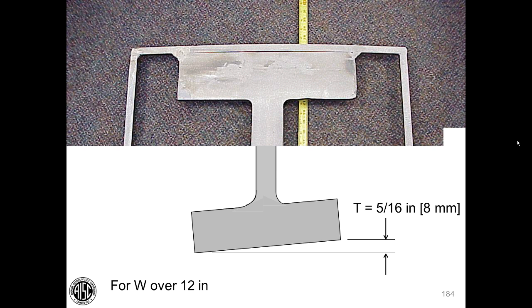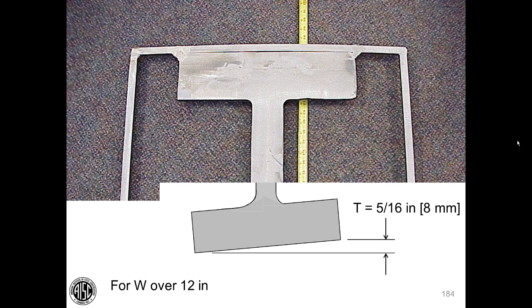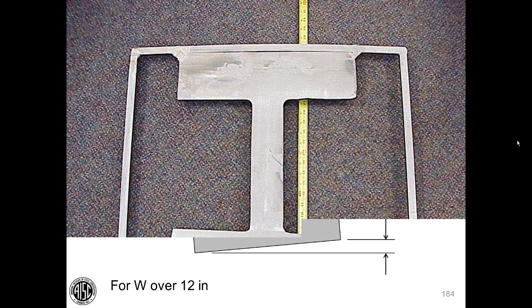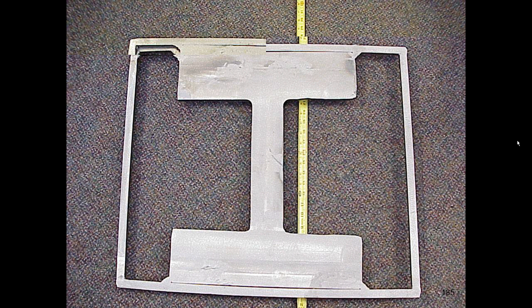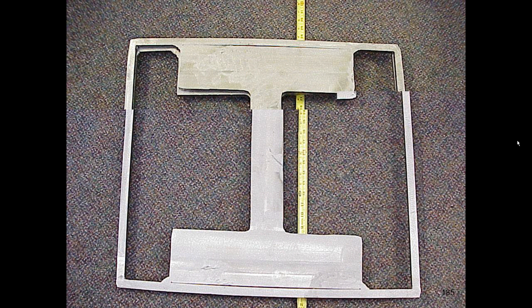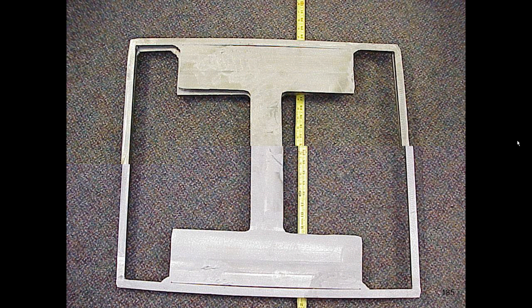And as you add sections together on this architecturally sensitive application, you're going to get members that don't line up. Owens was smart enough to make some mock-ups. And they showed with their mock-ups that the standard acceptable tolerances on the wide flange shape, as well as the distortion that was going to be created by these welds, was going to result in members that didn't line up.